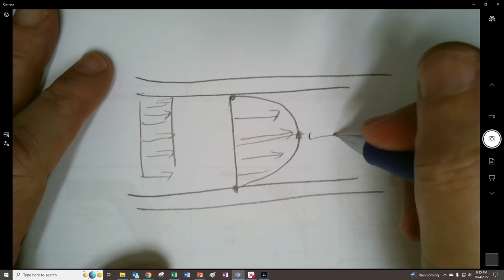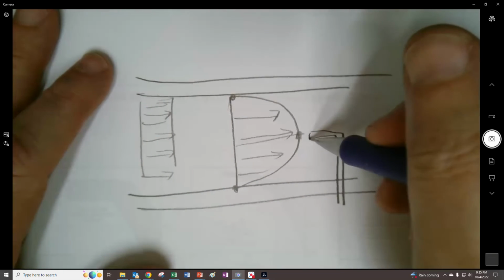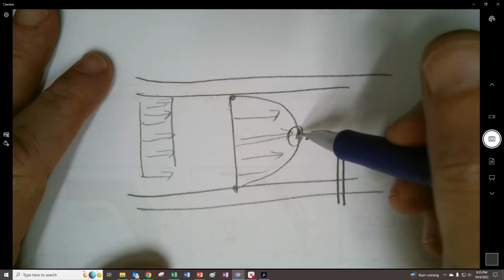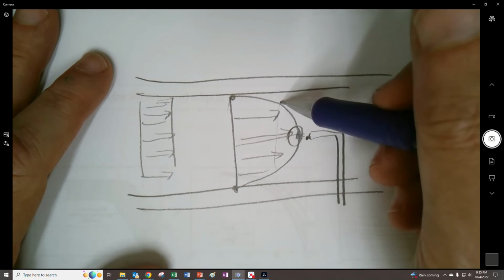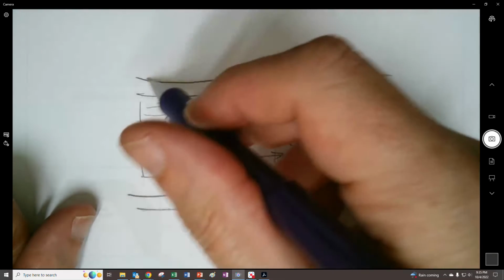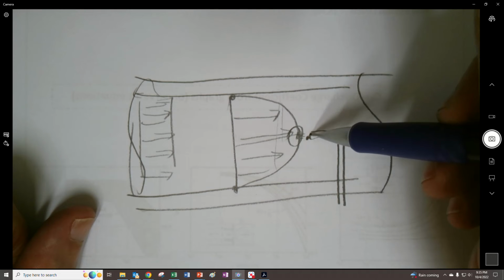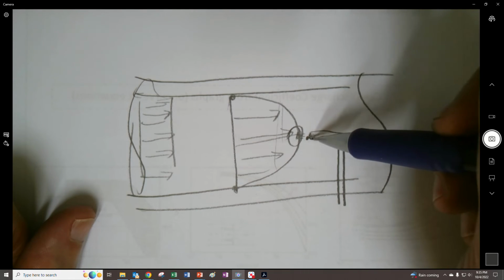So when we have a pitot tube, and hopefully it's a long, slender pitot tube so it's not disturbing this too much, we get a stagnation pressure. That's really going to measure the velocity at the center, which is not indicative of what the velocity across the whole thing is going to be in most cases, right? Especially in a large duct or something along those lines. Pitot tubes are much better for gases, I think, than for liquids. There's some vulnerability about what's happening in and around here, but it's a pretty accurate measure.